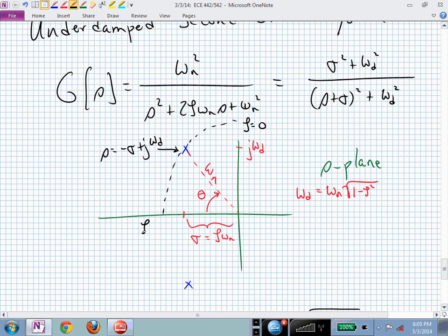If those poles both swung around here by increasing the damping, then zeta is equal to 1 when they become real, two real equal poles. And the underdamped case is when we have a zeta value between 0 and 1, meaning this angle theta could be either 0 degrees, purely real poles, or it could be 90 degrees, purely imaginary.